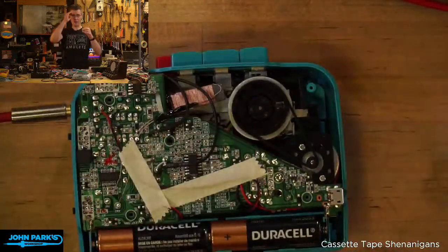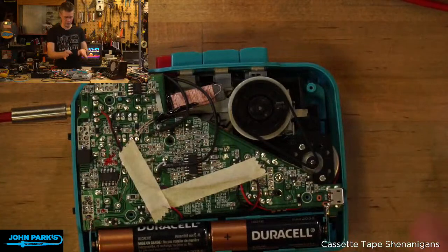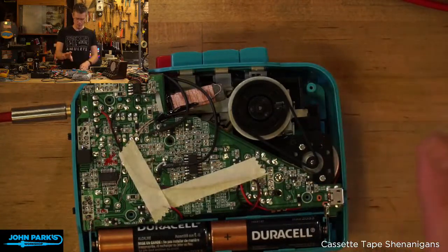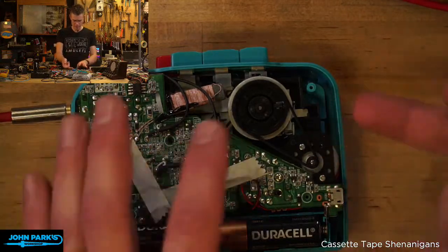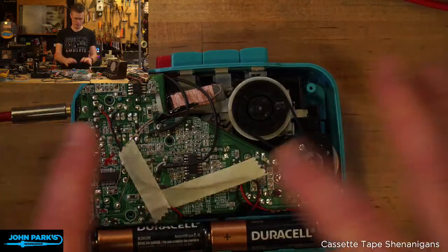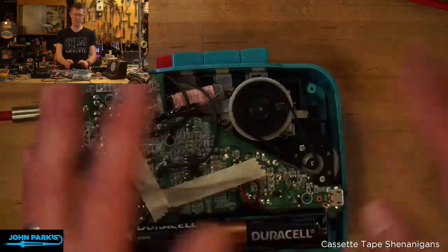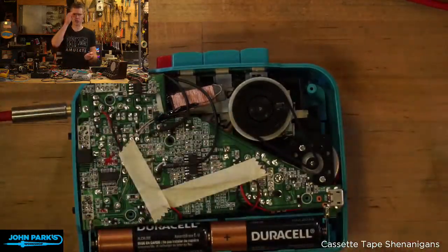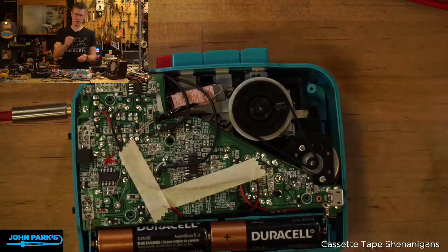Sort of the basic foundation of figuring out, okay, where are we going to go in and connect up to be able to adjust this motor control. You could do it by following the motor and seeing where it's plugged in. I didn't have to. Someone had done this exact one already, so I didn't need to explore. But you could also approach it kind of like circuit bending, where you find a ground and then just start prodding around, bypassing resistors or changing the resistance value to see what happens.